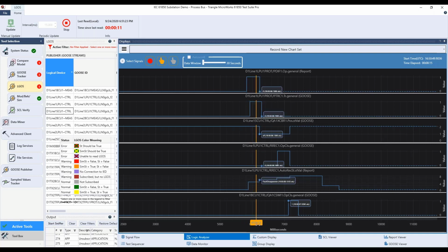After a while, we have the breaker that opens, which sets the recloser in the state fault disappeared. As a result of that, also the operate and the trip signal go away. We wait for the reclose time. After that, the recloser activates the op close. The recloser goes to the state waits to complete, so he waits until he gets the close position back from the breaker. He takes the op close away.